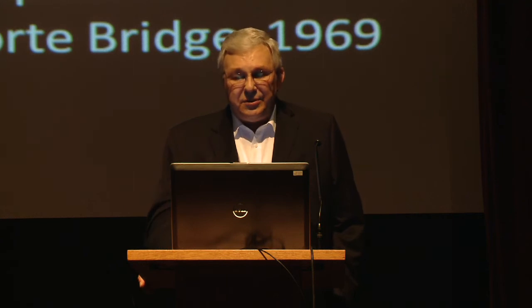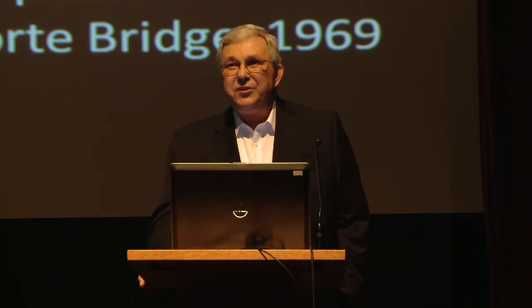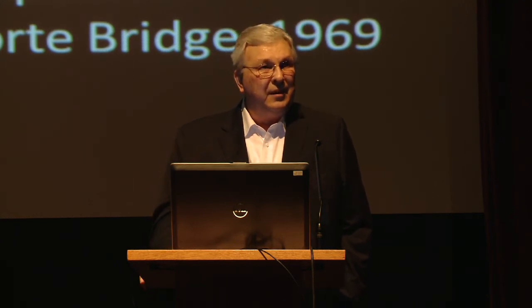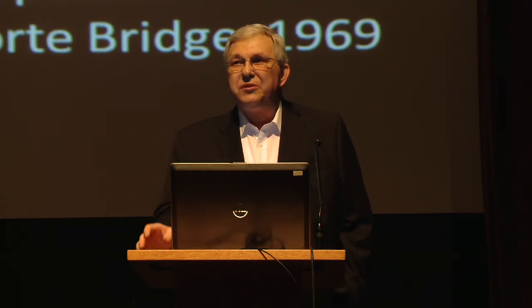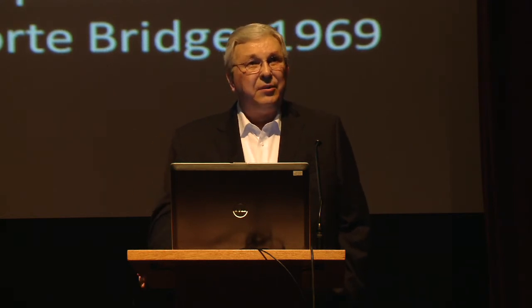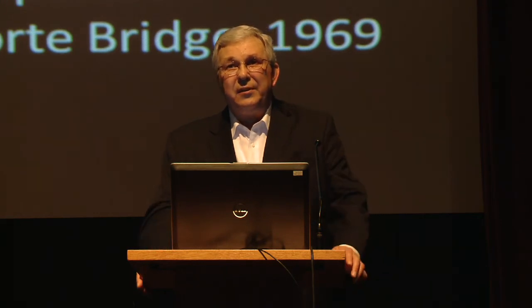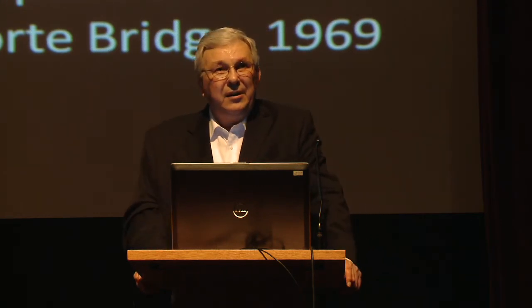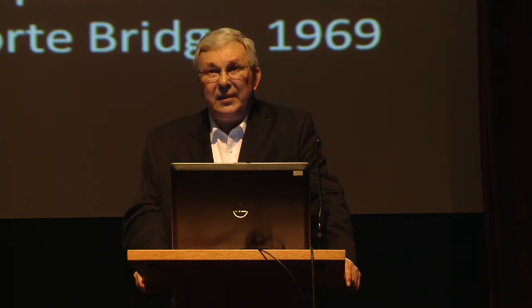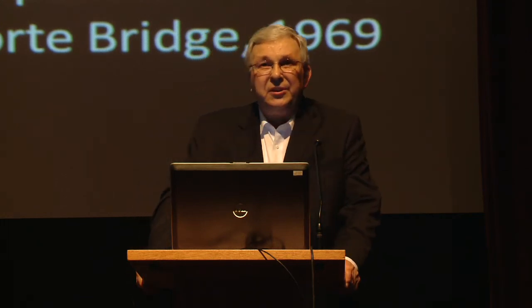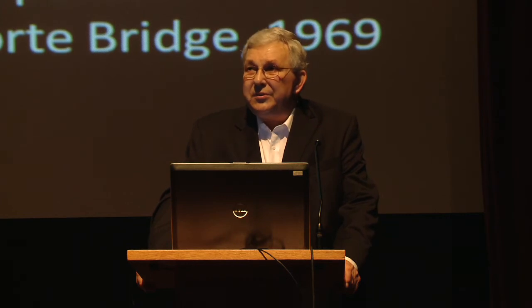But in the case of bridges, the suspension bridge was an alternative. Anything you wanted the cantilever to do, the suspension bridge could do. And so effectively, anything over about 1,500 feet wasn't going to be a cantilever, it was going to be a suspension bridge. To this day, the suspension bridge is the one that you use for longest distances.